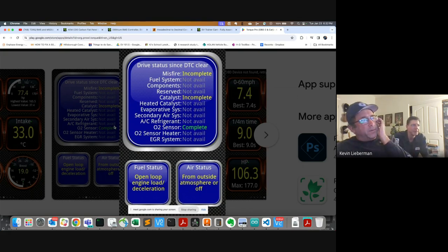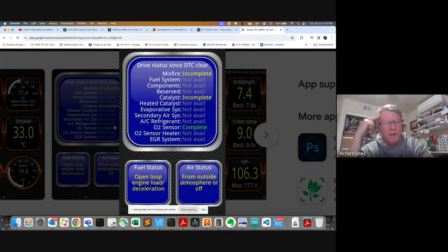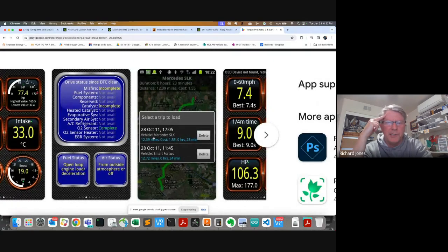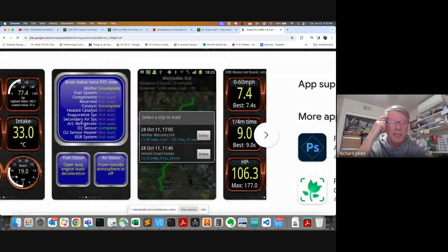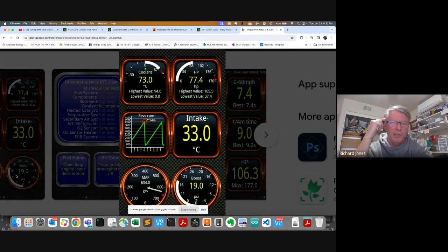To be honest though, since you've got that AEM display, that's the most direct because it's connected to the CAN bus directly, and it's using that DBC file with a signal that says, this is cell 27's voltage. That's the closest you're getting to the CAN bus data coming off the dilithium or the motor controller for its temperature or RPMs. OBD2 adds another thing in between, which is the Bluetooth interface. And then the Bluetooth is going to an app running on a phone or a tablet. So it does add some extra stuff.